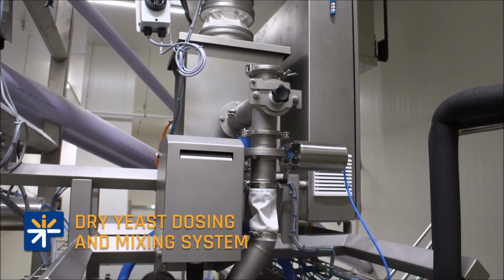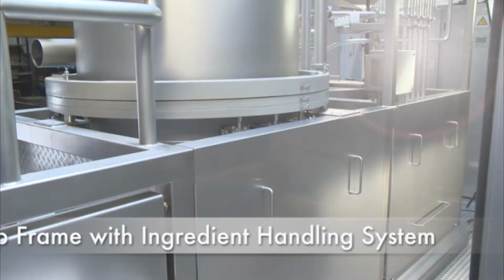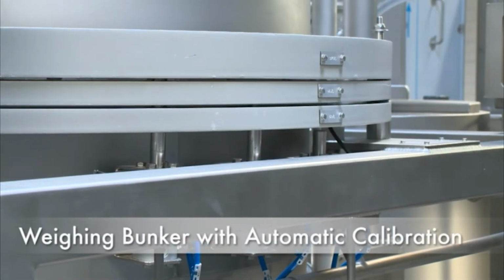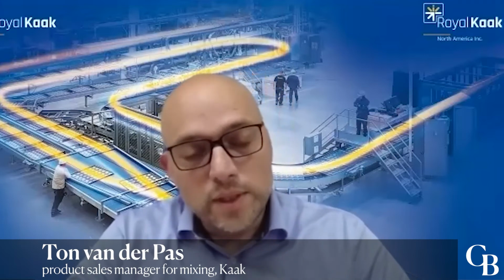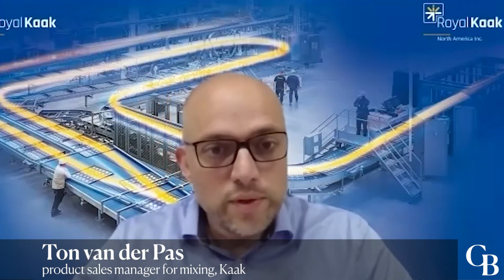What I said before, we are measuring the exact amount of ingredients which goes into the mixer. And based on that calculation, we know how much energy is added per pound of dough. So we never overmix or undermix your dough, and you don't mix on time. Another fact is that we measure the temperature of the flour and compensate for that with the temperature of the water.